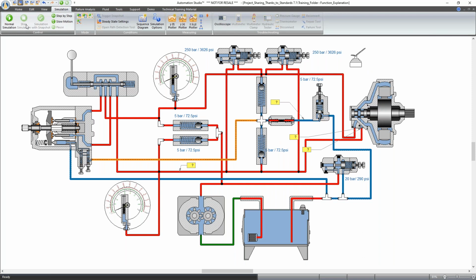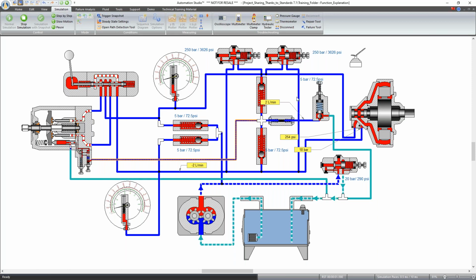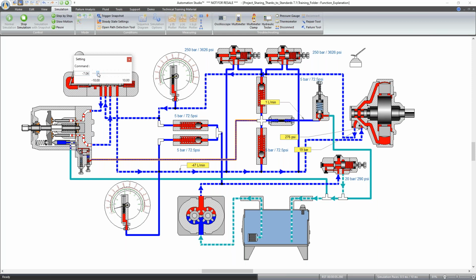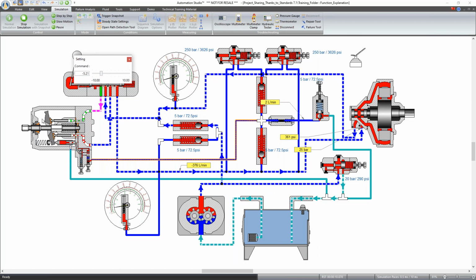Yes, there's something, Dennis. The motor we use is unidirectional. That's why you just have to use the lever on the left. We haven't added the bidirectional at this time. That's why there is no flow. It's okay. No, it's not a problem. Then it seems you're trying to put flow where you couldn't. You see that this is turning. And as explained, it's an open loop pump that we use with this radial piston motor.